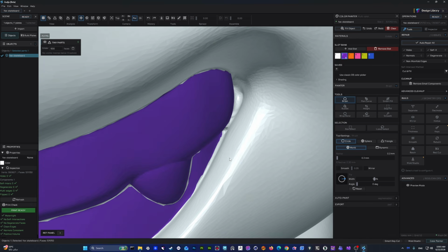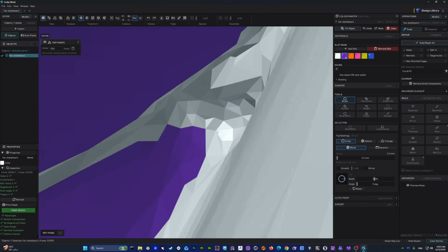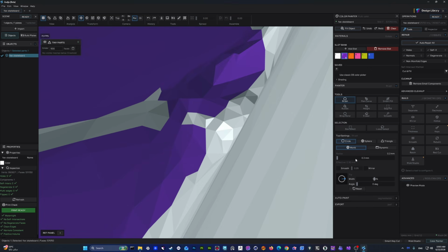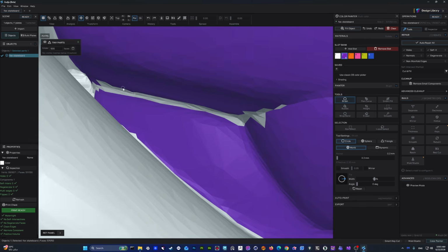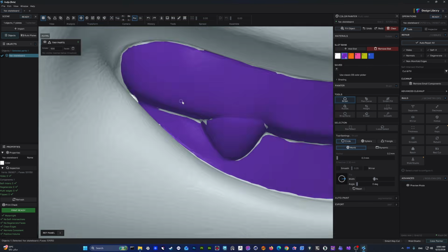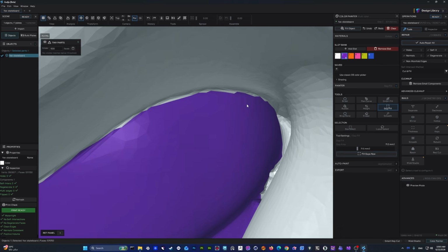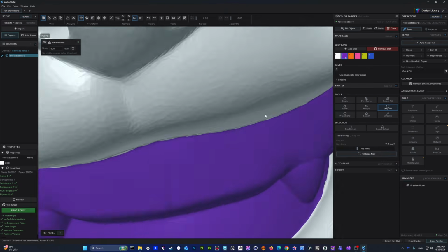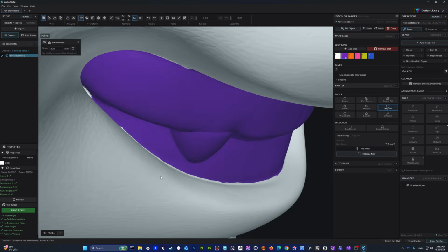so that's an important thing, as I told you in the last video. In a small part like this, if you put your mouse here and press Tab, you're gonna see the orbit focused on this. If I zoom, I can see everything inside, and the brush actually, yeah. And I go on another part and close it like this. And I'm gonna do a gap fill. All right. And as you can see, I have jagged edges here, and I don't want to repaint all of this. I just want to click, and that's it.